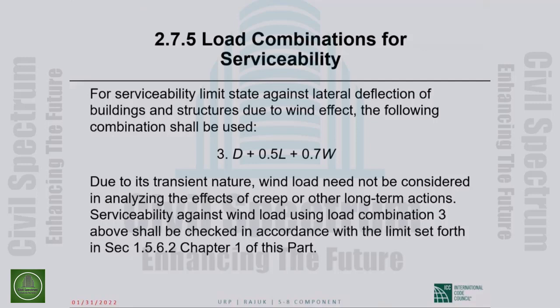The only time gravity loads will cause lateral deflections that will be additive to the deflections caused by wind is if you have very distinct lack of symmetry in your structure. In a symmetrical or near symmetrical structure, dead and live loads will not cause any appreciable lateral deflections.